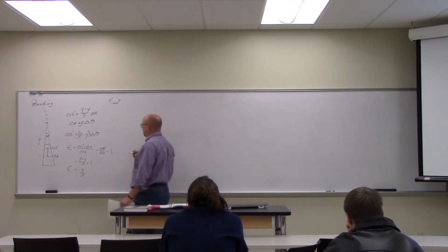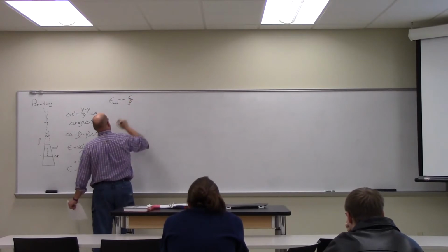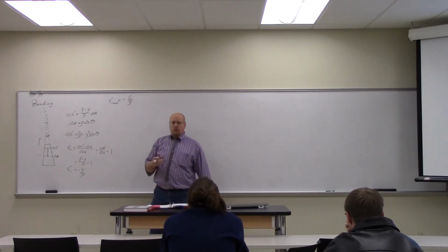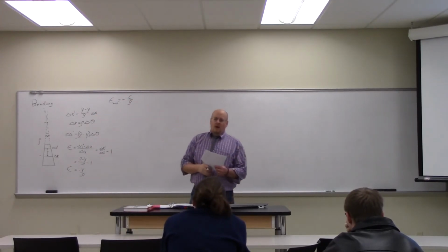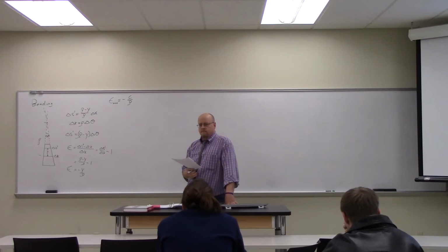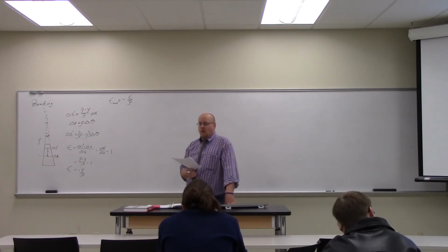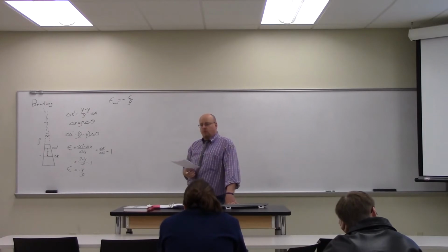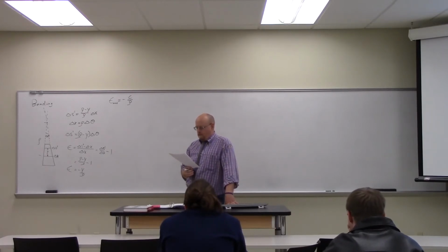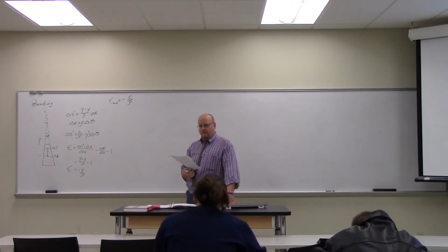Okay, if it were a round bar, the way we've been doing that would be minus c over rho. And c was the radius. Is the neutral axis straight through the middle necessarily? Not necessarily. We'll define where this neutral axis is in just a second. But in a round bar, it is right through the center, yes. Okay.